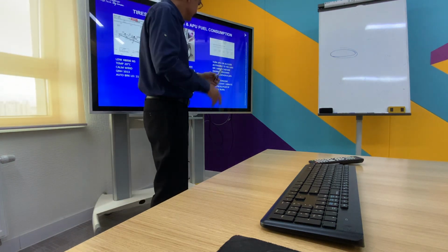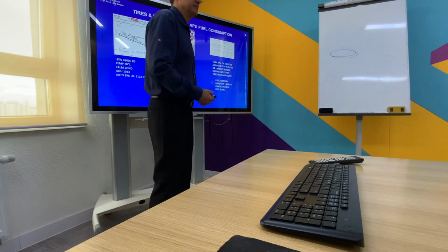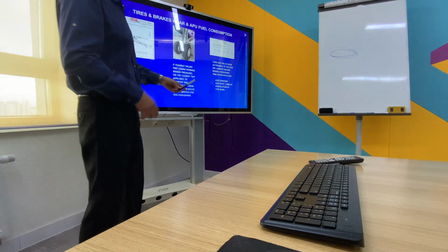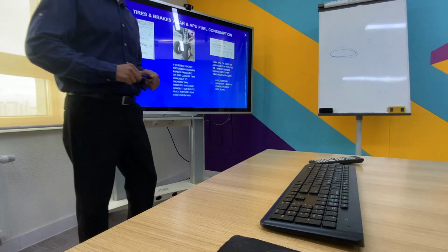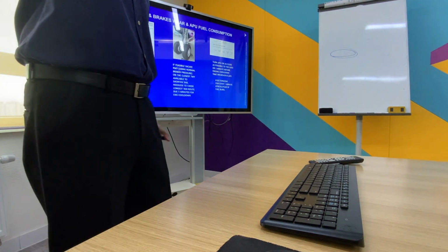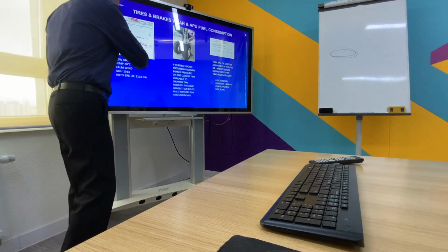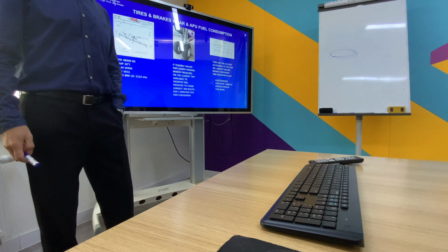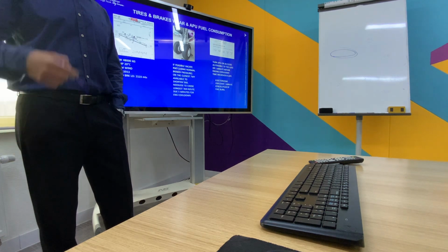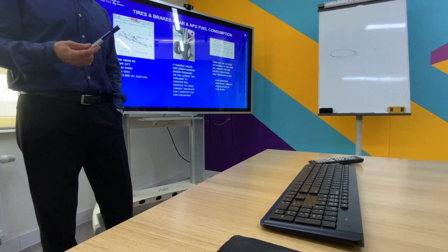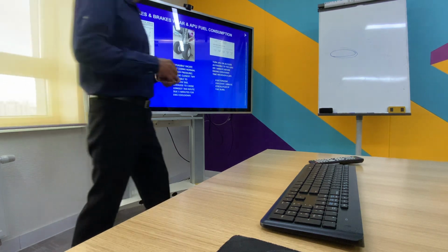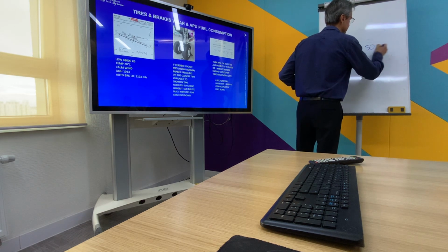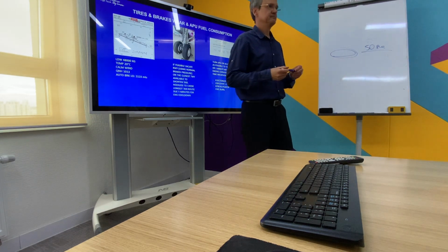I did a calculation for every minute with the APU running. In a year, we spent 6,700 kilograms of fuel. 1 minute. I see some pilots vacating the runway, so turn on the APU. No reason for that, and stay with the APU running 3 minutes. Okay? The APU takes around 50 seconds to come on the line.